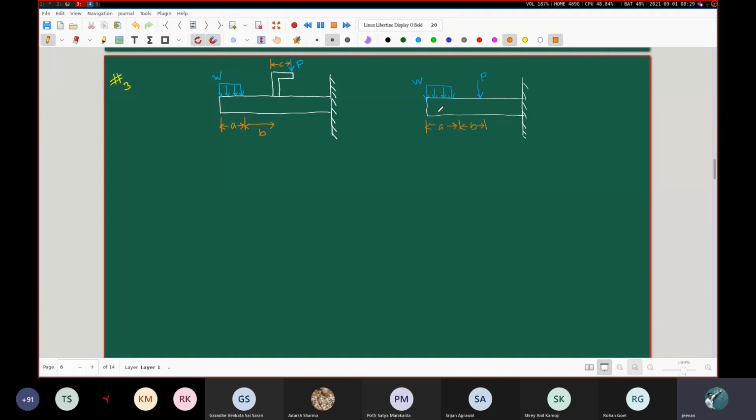That can be ensured only if I take a corresponding moment which was being contributed by the presence of the force here. And what is the value of that moment? We can understand it by taking the moment of this force about the point to which we want to translate it. I repeat, we can take the equivalent system by considering the contribution to the moment that this force was making, by taking the moment about the point to which we are translating. So this is our source, this is our destination. Take the moment about the destination.